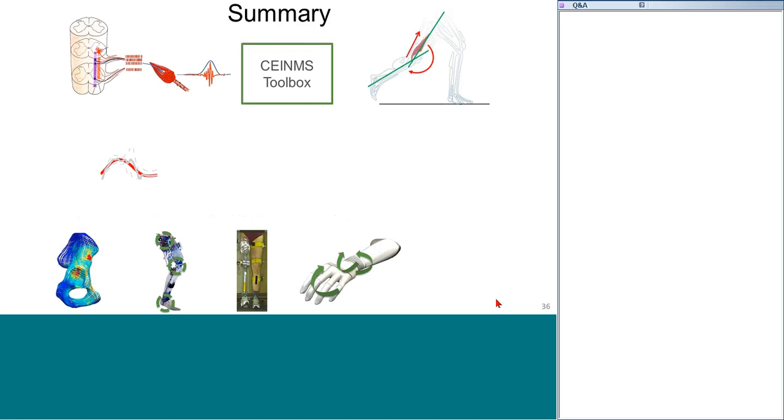We can then exploit the modularity in muscles to simplify the complexity of EMG data, and this allows us to implement proportional control in assistive devices even when EMG data may not be entirely available from the patient's muscles.